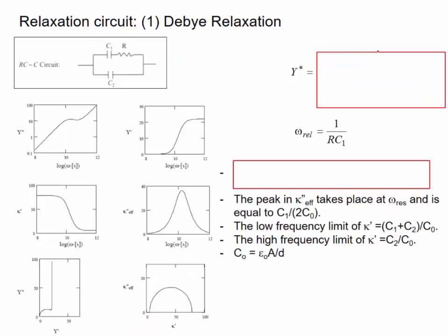And for the relaxation behavior, there are several circuit models in the textbook. We're going to review two of them. And one is the Debye relaxation model. So here you have a capacitor and a resistor in series, and there's another capacitor in parallel. And admittance, so let's say that this first one, what will be the Z of that? R plus minus j 1 over omega C1, right?